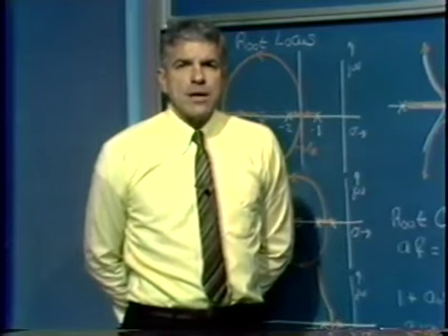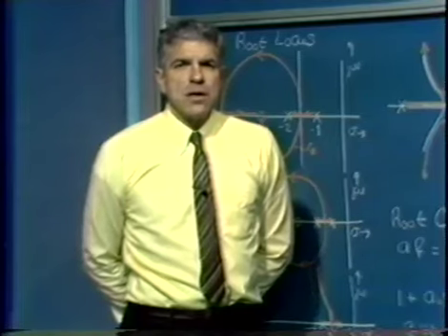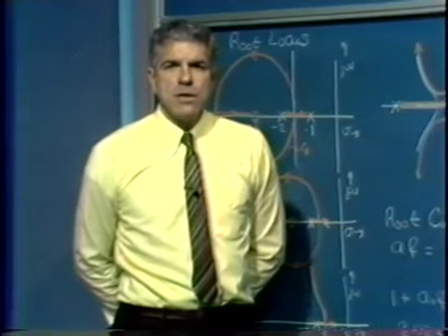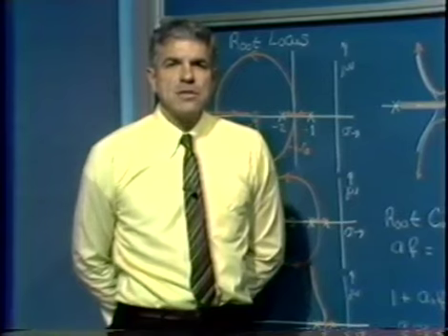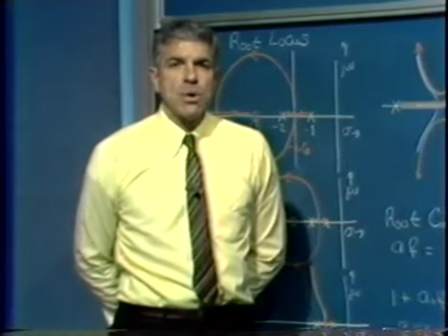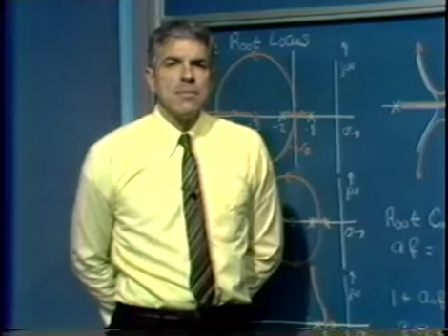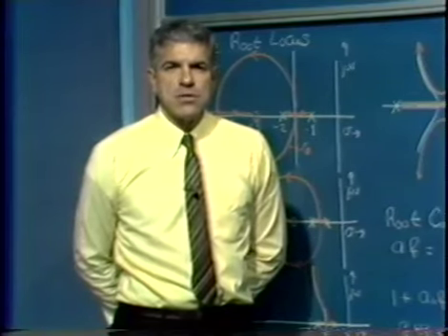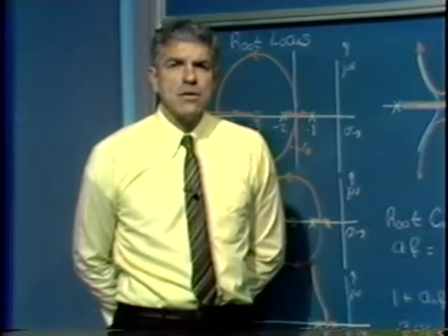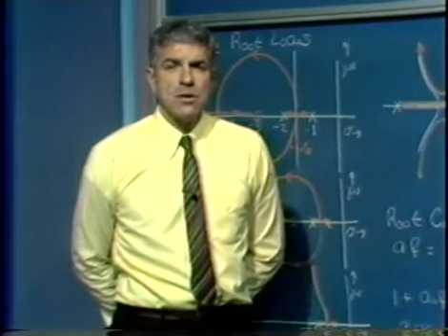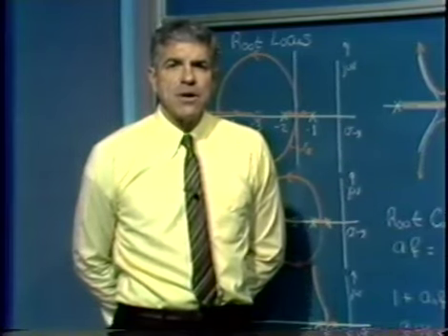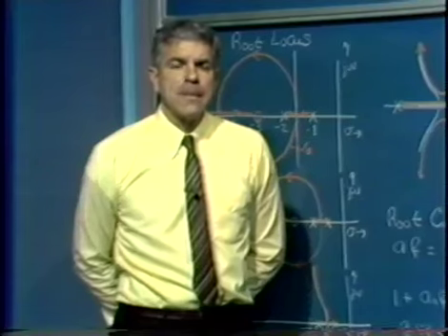And again, the thing to focus on is that the technique allows us really to look at the variation in any single system parameter. When we look at a root locus diagram, we're varying A0, F0. But suppose we have some other system parameter, and we're interested in how the closed loop poles change location as a function of variations in that parameter.